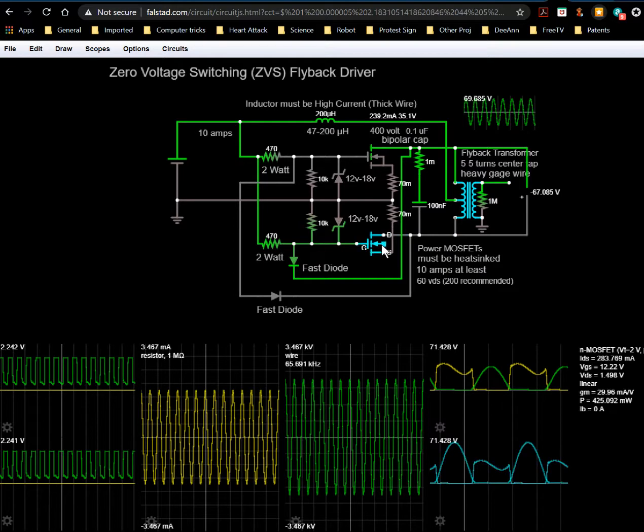Why is that? Because this transistor is turned on and this one is turned off. And that's 68 volts. Okay, well, how are we getting 68 volts when this is saying negative 67? It's because this capacitor is now not charged up with a positive here and negative here. This inductor has actually, because of the energy going back and forth between these two, flipped the voltage on this cycle. And again, it'll flip back later on, once the voltage goes this other direction.